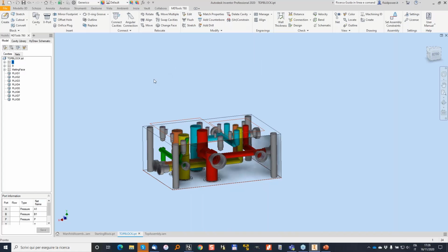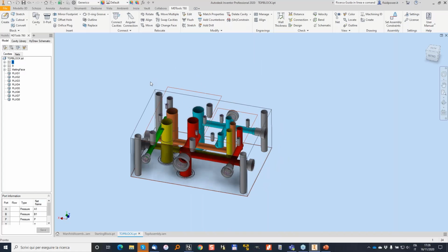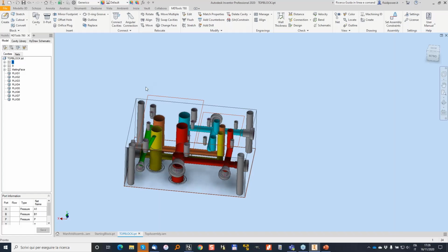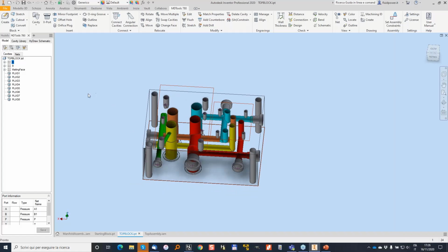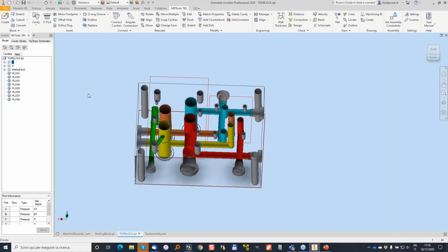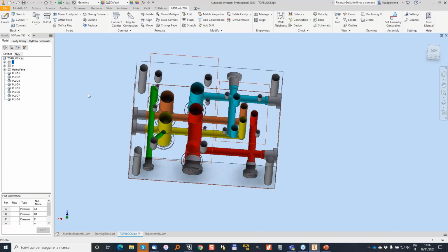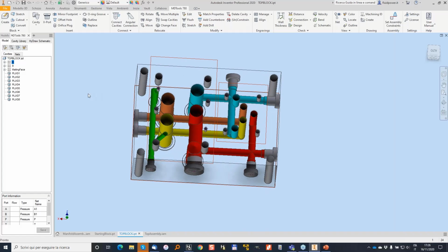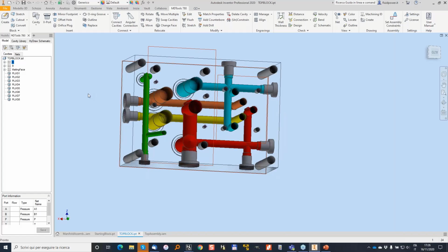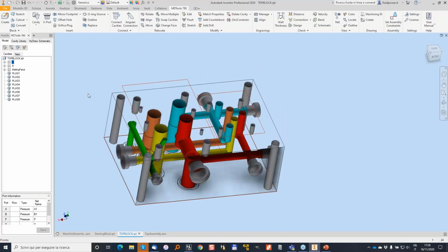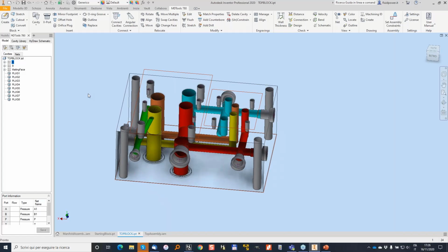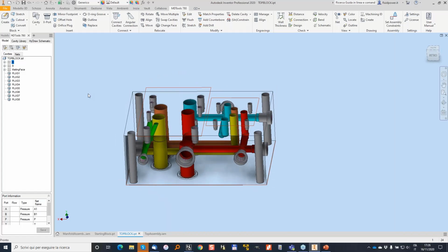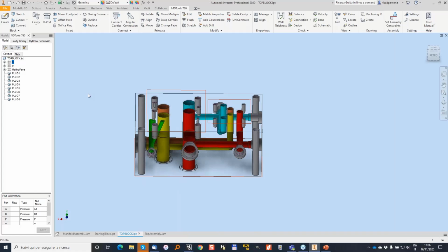To create the mating manifolds in SolidWorks, in those cases, either you create the footprint in the library, which is one option, or you can use other techniques, which I don't have enough time to show, but I will be happy to explain to SolidWorks users if they have any specific need. So basically, we can project the drills from one block to another directly in the assembly space.